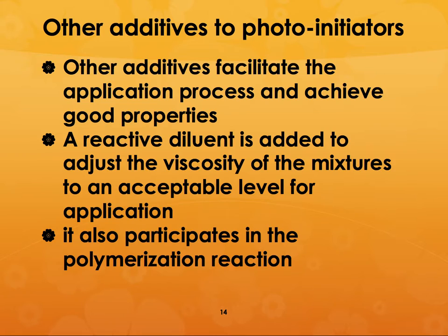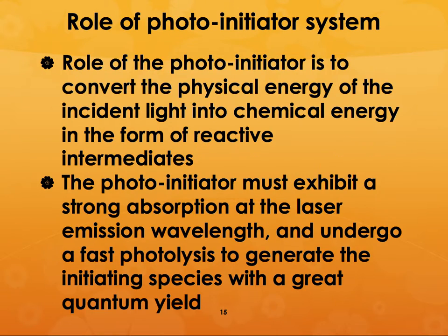So you might want to reduce the shrinkage, or you may want to get good mechanical properties. And you may also want to have a reactive diluent to adjust the viscosity of the mixture, so that when you spread it on the layer that has just been built, it gives you the right kind of viscosity. It doesn't just fall off, or stick around and clump up at different corners. It will also participate in the polymerization reaction.